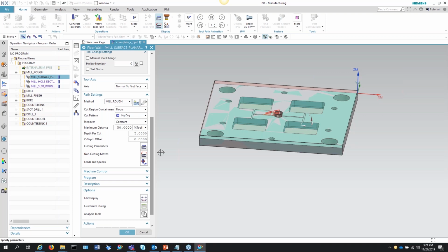But say this is a developed template to where it uses the same tool, same speed, same feed, same depth of cuts, and you have many different templates for different materials. So one thing that you can do on the administration side is you can remove that depth of cut and that feed rate so that your programmers use the template, but they don't have the option to go through and change those parameters on the fly.